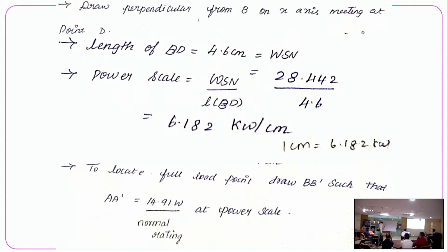So if we know the rated current of the motor, the full load current, we can determine the full load power, the rated power. From that we get the full load power factor, cos phi L. So we can draw OP as the full load current, which is at an angle phi with the voltage. The cosine of this angle is the power factor, and OP is the full load current. OP will definitely be on the circle, because the full load point will be on the circle.